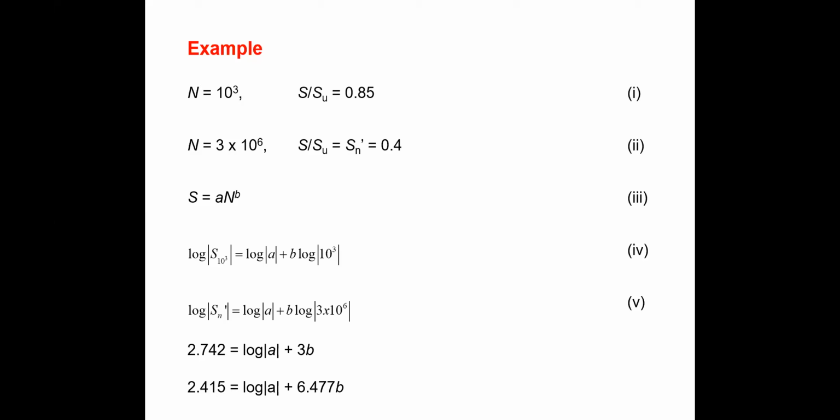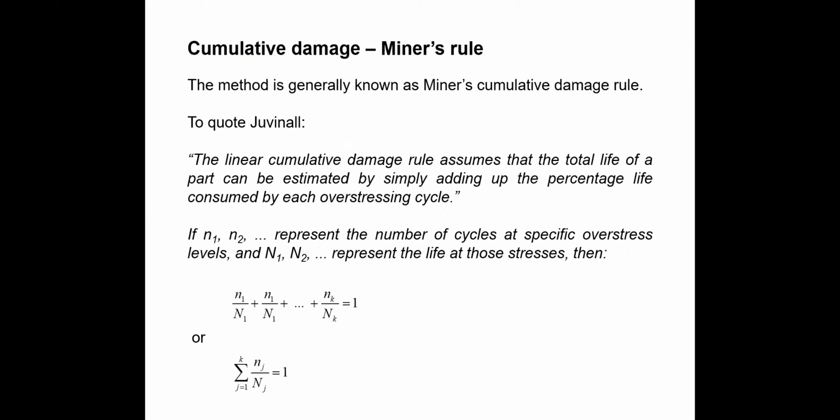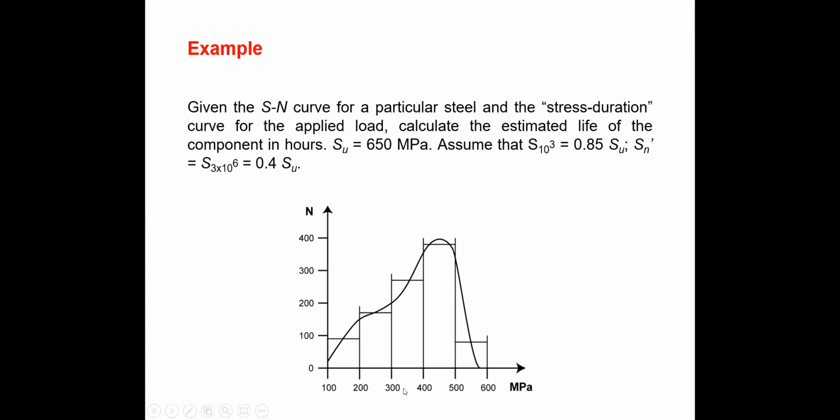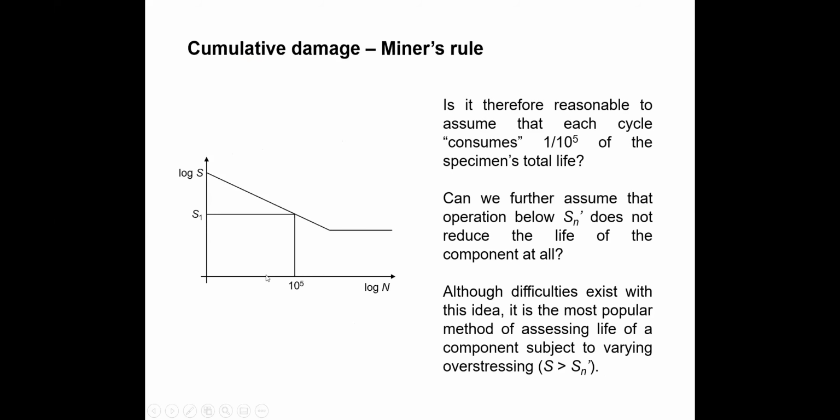No. Actually, if you remember when I explained here, we have different stress ranges, no? With this question, you can see different stress ranges. We will consider the mean values, 150 and 250 like that. With this stress, we should know the total number of cycles to break this sample with this stress range.